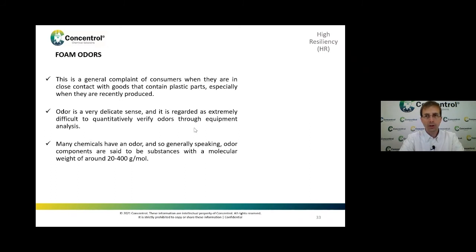Another important topic is the odor of a foam. It's a general complaint of consumers when they are in close contact with plastics, especially when they are recently produced. It's a very delicate sense and it's regarded as extremely difficult to analyze quantitatively using analytical equipment. We also know that most chemicals have an odor, and that, generally speaking, components with a molecular weight lower than 400 grams per mole are possible odor sources.